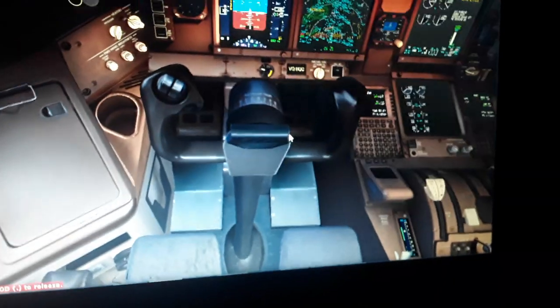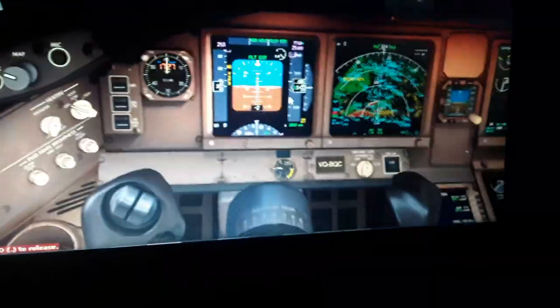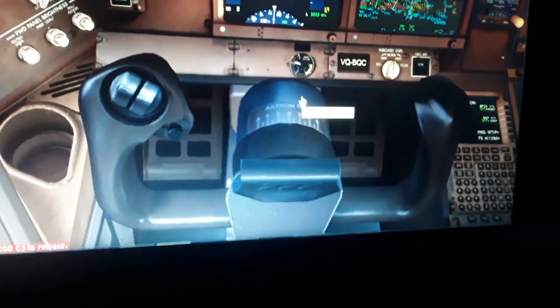So this is the horizontal trim stabilizer you can use. Over here you will see this is the disconnect for the auto trim. If you have a failure of the autopilot and the auto throttle auto trim function, you can use only the manual over here. So this is the manual trim for the horizontal tail. Over here you pitch up and pitch down. Also you have the aileron trim, so you can see the ailerons and the rudder trim here. So this is the horizontal tail trim, and this is the disconnect, and this is also the normal and alternate horizontal tail trim tab.